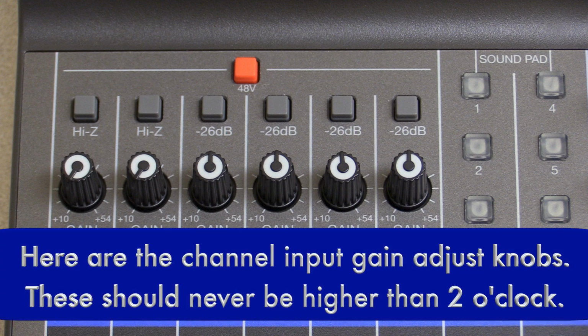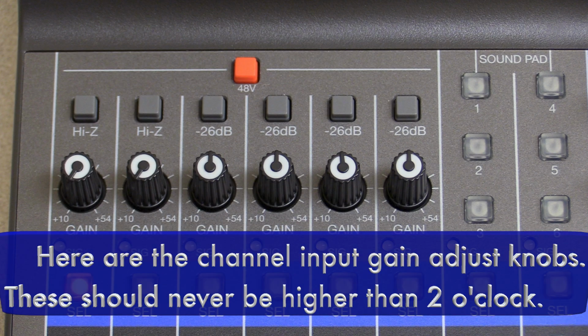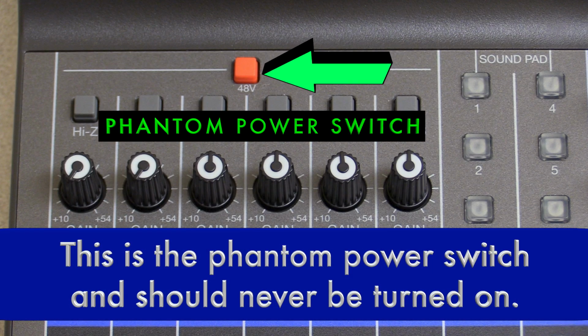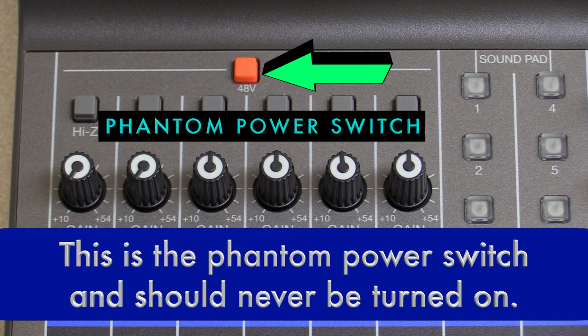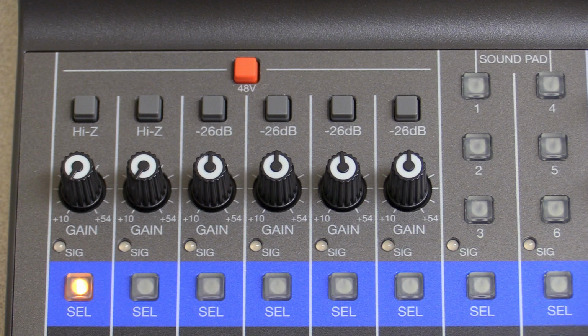Here are the channel input gain adjustment knobs. These should never be higher than the 2 o'clock position. The 2 o'clock position might be too high in some cases, so adjust until your audio is loud enough without distortion. Above the gain adjustment knobs is the phantom power switch, and this should never be turned on. Our mics don't need phantom power, and you can potentially ruin equipment by turning it on.